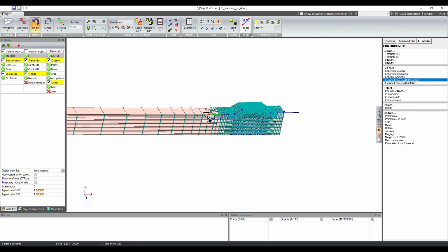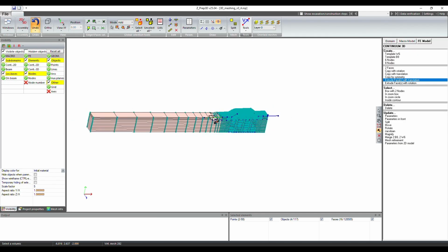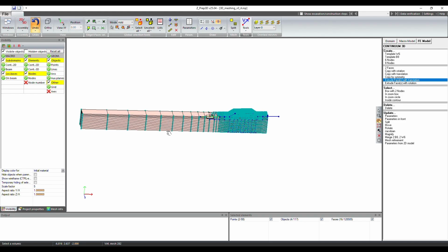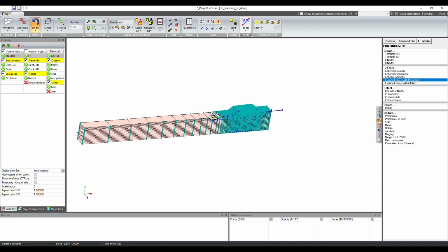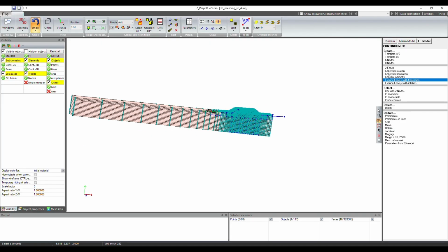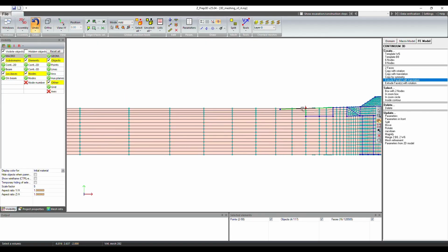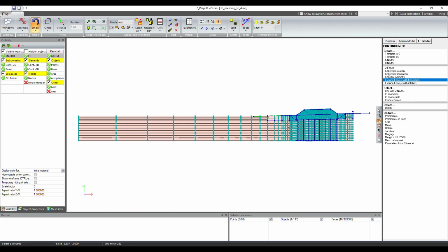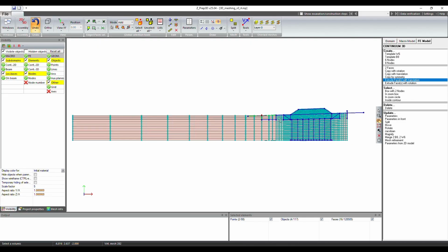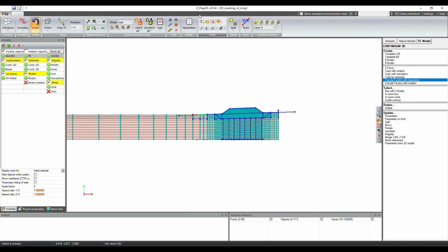And this way you get at every extrusion step a slightly larger step. This way we can assure that the boundary conditions are really far away. Additionally, we extruded perfectly horizontally, so we do not follow the terrain surface anymore. We do the same on the other side, but I'm skipping this in this tutorial.